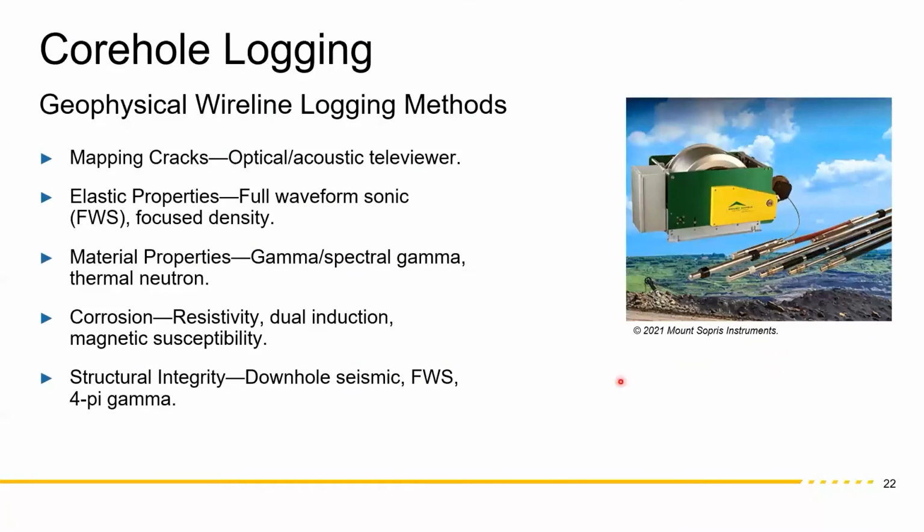And you get, of course, the cores coming back. So again, I'm going to use what's known as borehole logging, or what we call core hole logging technology. I'm going to use basically optical televiewers and acoustic televiewing. I'm going to show some examples for mapping cracks from the core holes, and looking at elastic properties using sonic and density tools, which is similar to the drill shaft environment that Bernie showed with the cross-hole sonic and 4-pi density. These are other logs which I don't have time to show examples of right now, but we look extensively at this whole idea of borehole logging.